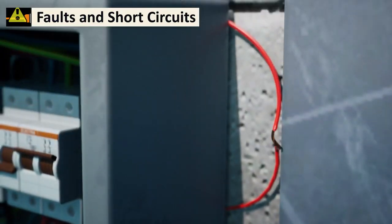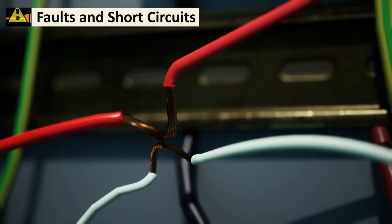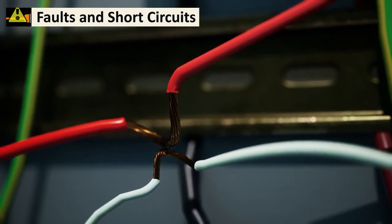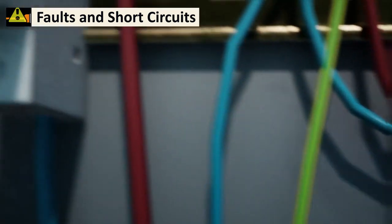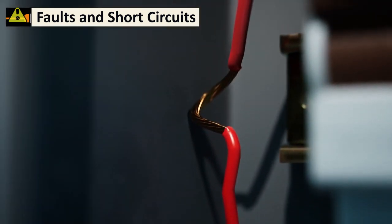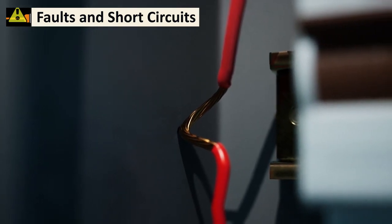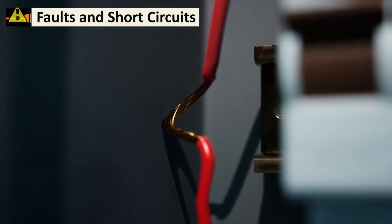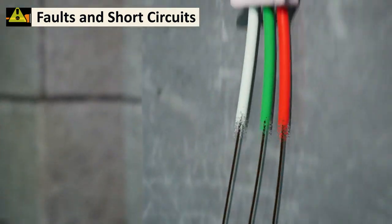Technically, a ground fault is a type of short circuit, but in electrical safety, the term short circuit usually means that the energized or hot wire makes contact with the neutral wire, giving a low resistance path back through the normal circuit wiring, while the term ground fault means the hot wire makes contact with either the ground wire or some other part of the equipment, providing a low resistance path outside of the normal circuit. Both are typically caused by faulty or damaged wiring.